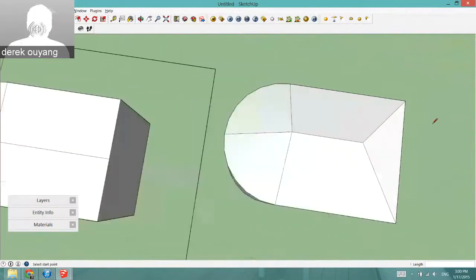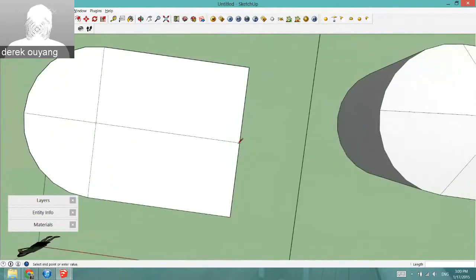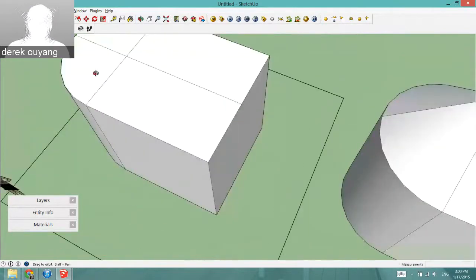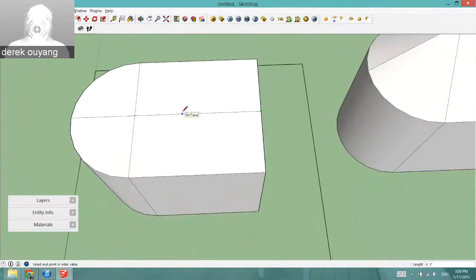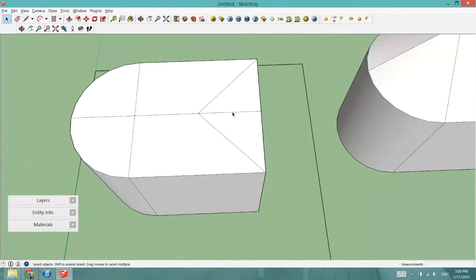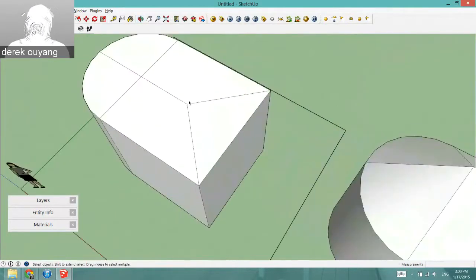And then to make these 45-degree lines, give ourselves a guide measurement. We know that this distance is 5 feet from the midpoint to the edge. So we're going to go inwards 5 feet. We've given ourselves a node right here, which in fact was also just the midpoint of the line we had here. And from there we can go off to the edges. We can delete this line we won't be needing in the final object.